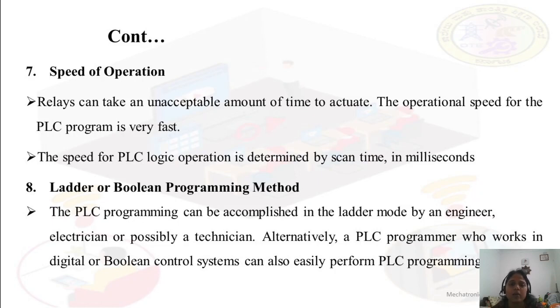PLC programming can be accomplished in a ladder mode by an engineer, electrician or possibly a technician. Alternatively, a PLC programmer who works in digital or Boolean control systems can also easily perform PLC programming. In PLC programming, we have different programming languages like ladder programming, instruction list, and functional block diagram, etc. The commonly used programming languages are functional block diagram and ladder programming.